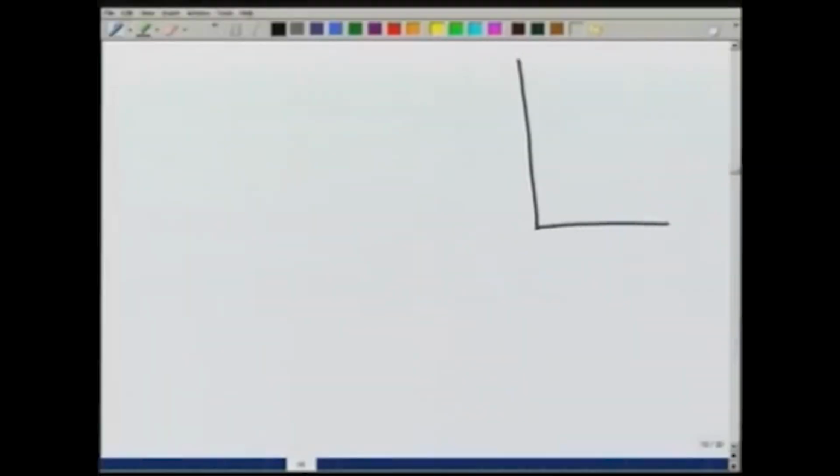There are relations between k, n and the moments of the IUH. So, if this is the unit hydrograph, then if we take the moment of this curve about the origin, those moments can be shown to be functions of n and k.